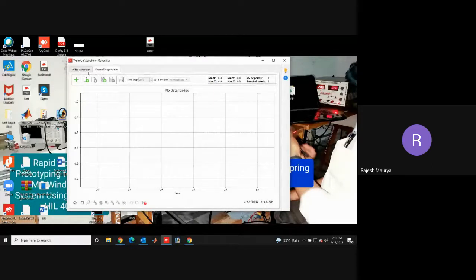But here in real-time simulation mode, this option is given on SCADA. Why is it given on SCADA? As we know, through SCADA we can change parameters during runtime. So that's why it is provided in SCADA, so that you can change the PV panel type while the simulation is running. It's not that it will remain fixed for the entire duration of the simulation. You can change from a normal PV panel type to shaded PV examples. So that's why it's been provided on HIL SCADA.